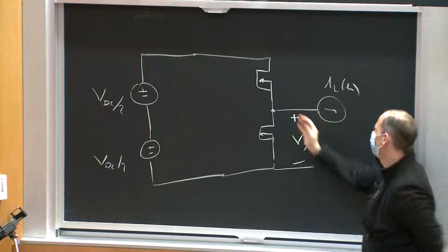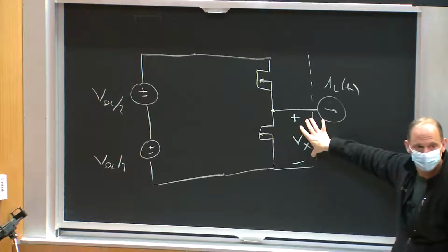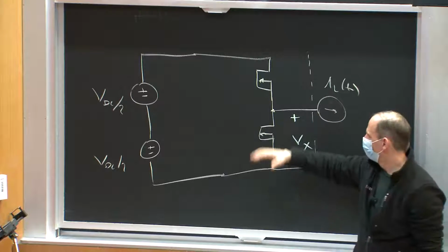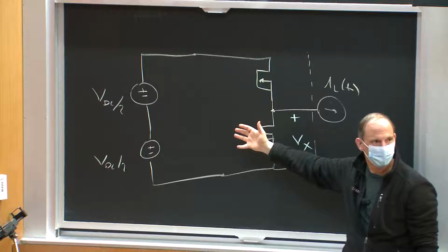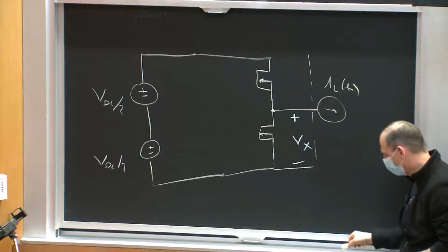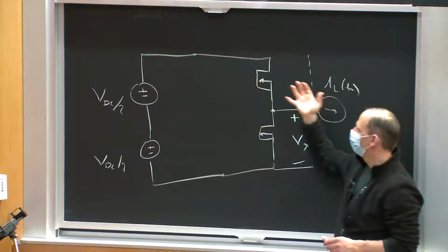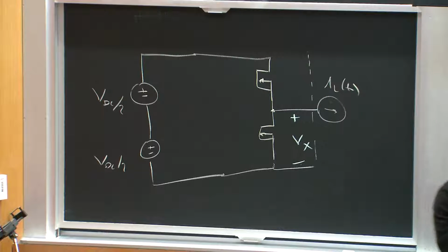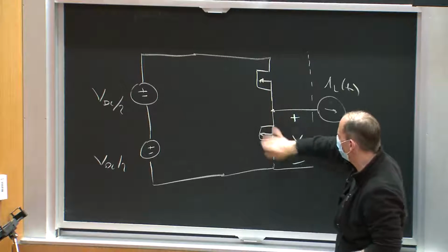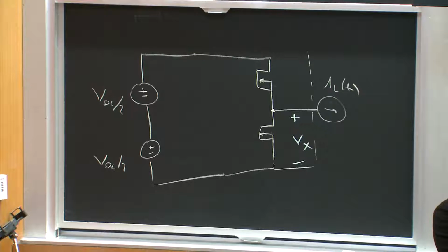Why? Because, you know, I do have EMI going out towards my motor, right? So maybe I want to reduce that dV/dt. Or maybe I want a PWM at pretty high frequency with high efficiency. And this is a high power system. Okay, so how could I do that? Here's one thing you could do. Maybe we can look at this thing and add some auxiliary circuitry that lets me switch between these two devices anytime I want, but will give me a soft switch transition.